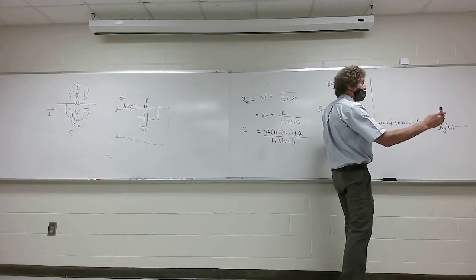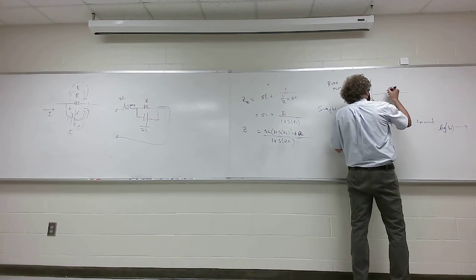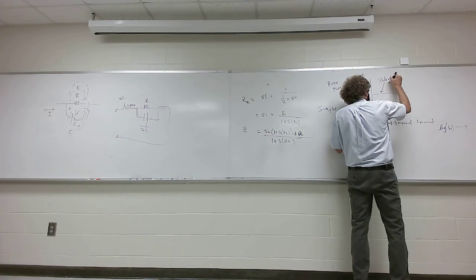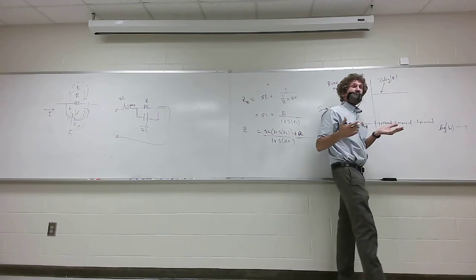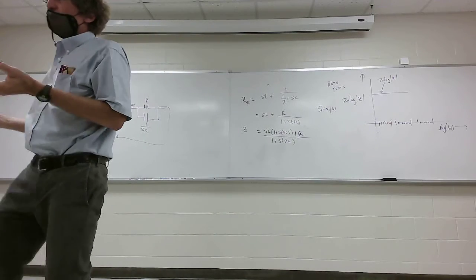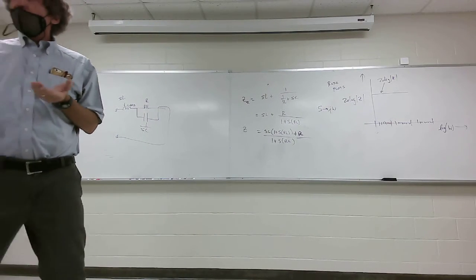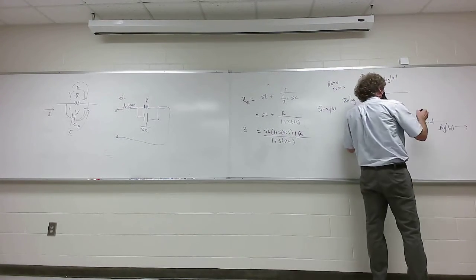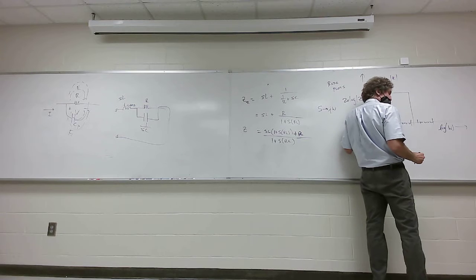That's that. And here's what happens with resistance. You start off, and this line will just be 20 times the log of the magnitude of R. So if you have an R of 10, the log of 10 is 1, it would be 20. But we know that's 20 times the log of R. It's going to stay there until it hits this point right here.